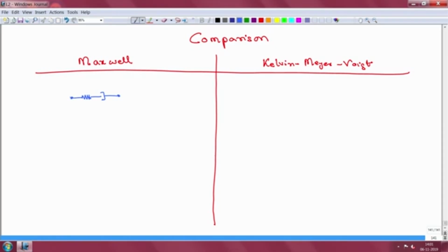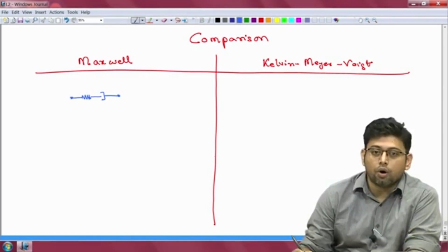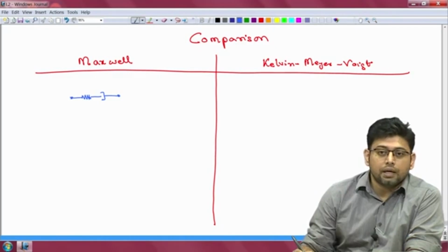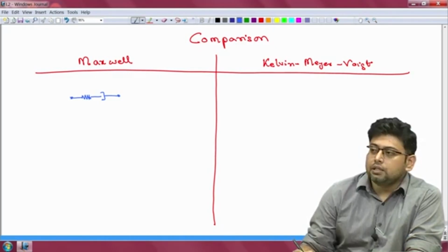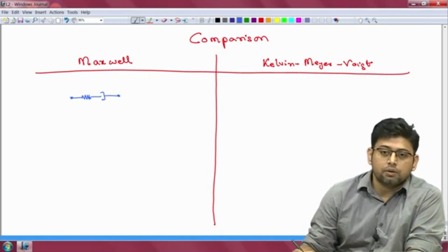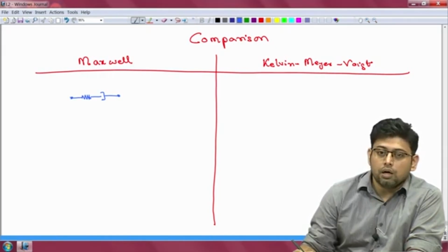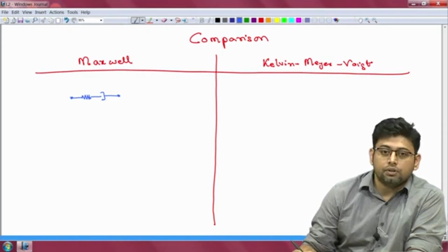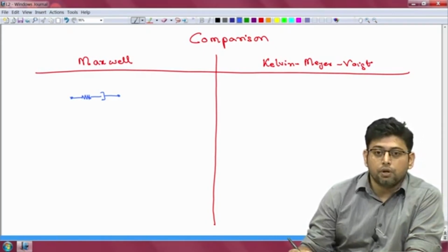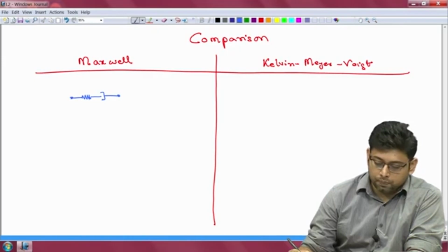So, we have not asked ourselves what is it at the atomic scale which makes this particular system viscoelastic. Rather, we are saying that we will phenomenologically introduce a couple of different models, and we will see whether or not they are applicable in our case. Right. And this need not be restricted only to polymers. This could be applied to any other system where there is a phenomenological match between our model and its curves or its responses with the real material response.